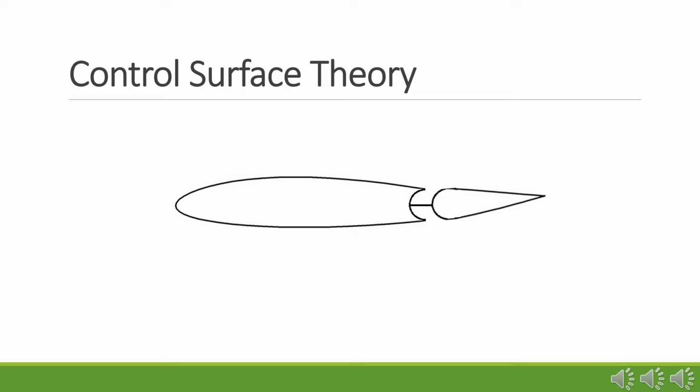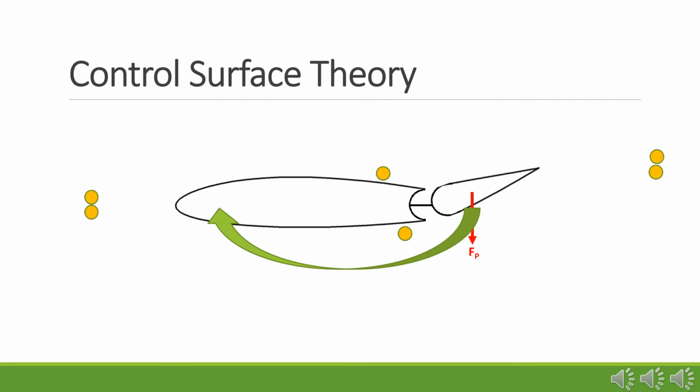If the control surface is rotated in the opposite direction, the normal force and perpendicular force are also changed. The drag force still acts to slow the aircraft down, but the perpendicular force now acts in a downward direction, which would cause the flight surface to also rotate downward.